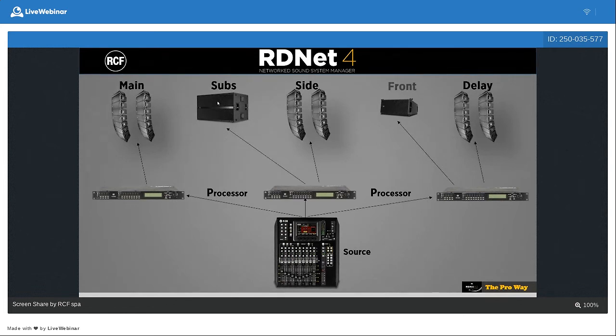To do a sub-arc in order to spread the energy of the low frequency in the audience area. This is a common technique to have a constant coverage in the low frequencies. So to make a sub-arc with 10 subwoofers, we will need 5 audio feeds. So we will need 1 processor just for the subs.